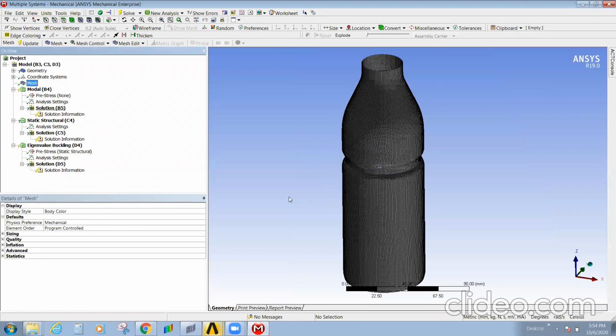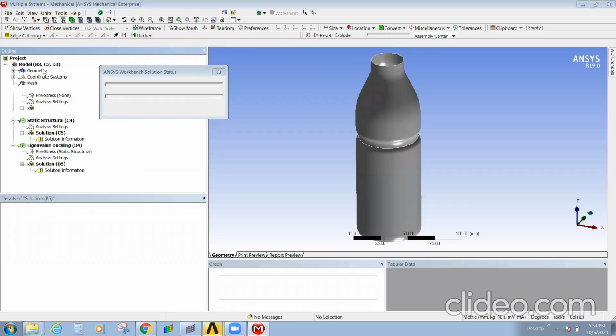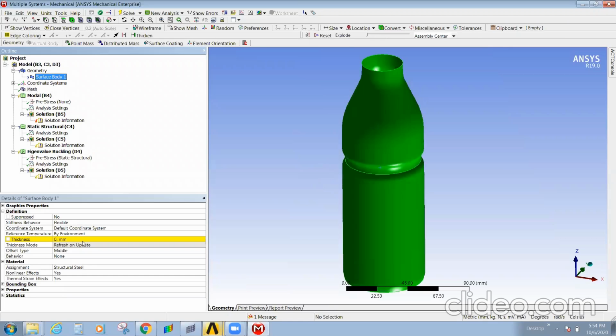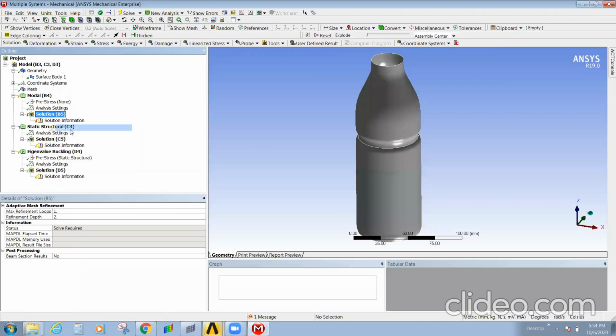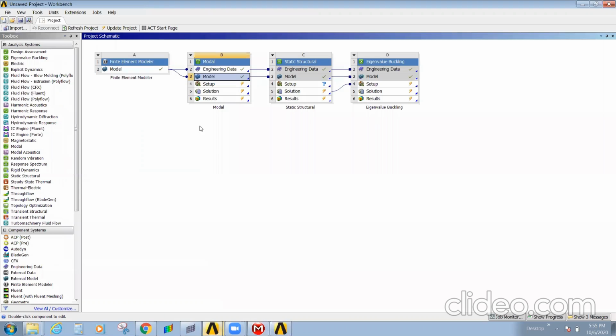So I want to ensure whether this mesh is connected entirely. The problem is the surface thickness or your mesh thickness, because it is a 2D mesh, so your surface thickness also will matter. So I have given 25 mm, and I'll solve for this to check whether each loading condition has the same result.